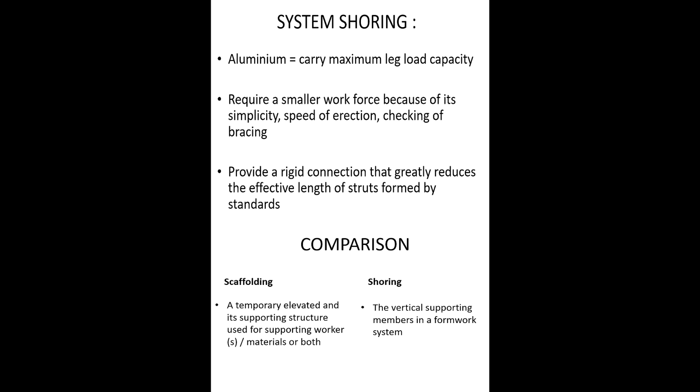It also has a comparison between scaffolding and shoring. I will explain the scaffolding first. It is a temporary elevated platform and its supporting structure used for supporting workers, material, or both. For the shoring, it is a vertical supporting member in a formwork system.